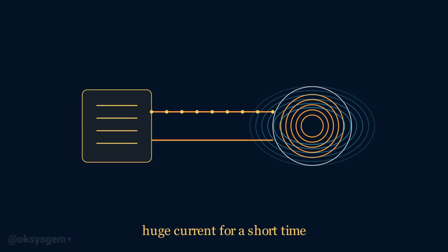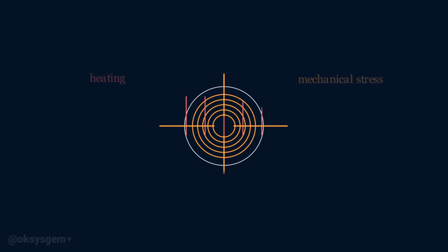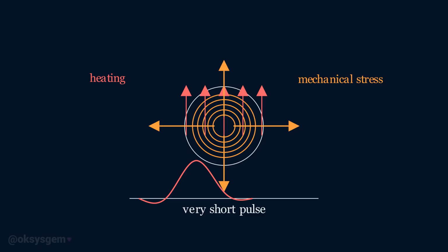This helps because many of the problems limiting magnet strength depend on time. A huge current heats the conductor. An enormous magnetic field also produces equally enormous mechanical forces inside the coil. Different sections of the magnet effectively push and pull against one another, placing the structure under extreme stress. If the magnet had to survive those conditions continuously, the required cooling and structural strength would become incredibly difficult. A short pulse allows researchers to briefly reach fields much stronger than many steady-state magnets can maintain.